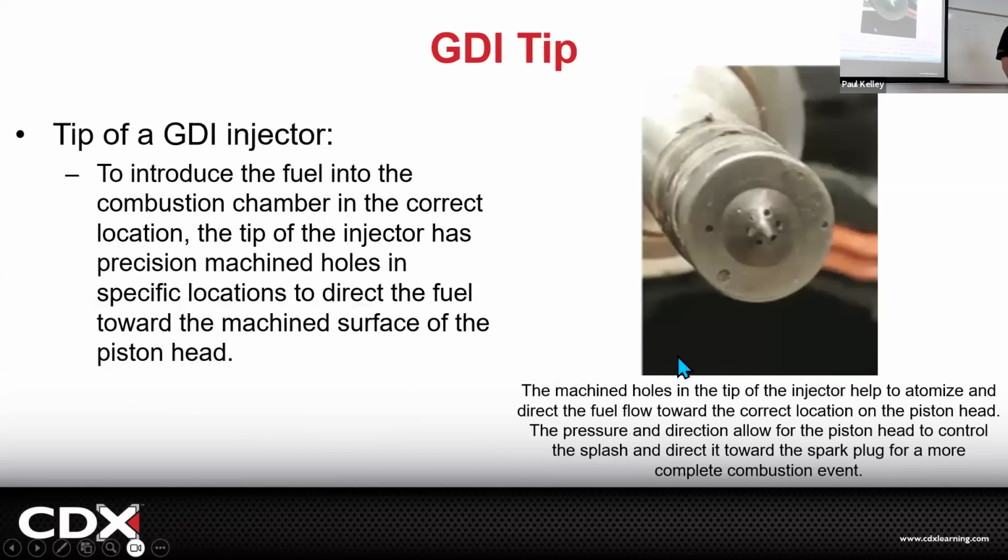Kind of interesting. And then the tip of these, because these holes are so small, they can tend to get carboned up a bit easier. So remember that whole top tier fuel discussion? The top tier fuels have cleaning agents to keep these clean. If you'll be running some cheapy fuel, Arco 87, which I'm kind of trashing Arco somewhat as a joke, but maybe legit, if you clog up these injector holes, you're probably not going to get those clean. You're probably going to get those replaced.